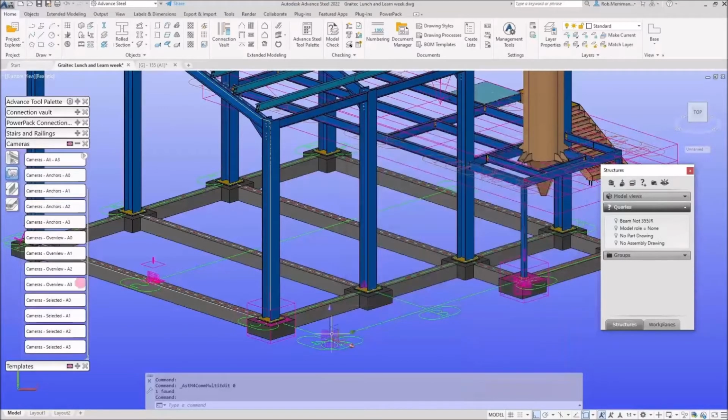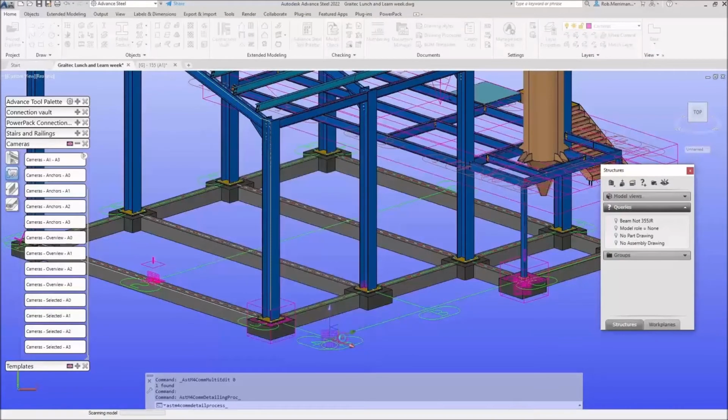We will run another drawing. And now, because this style enables holes to be shown, it will go and check the management tool, because the style says, yes, I'm allowed to show holes. The management tool says show holes on GA drawings, and then the system will put the holes in for me.